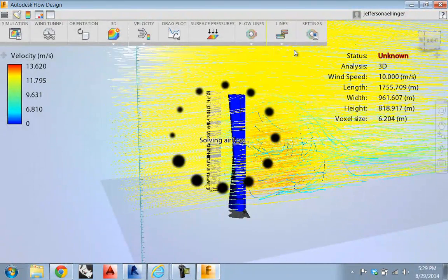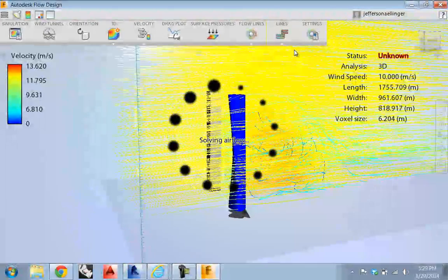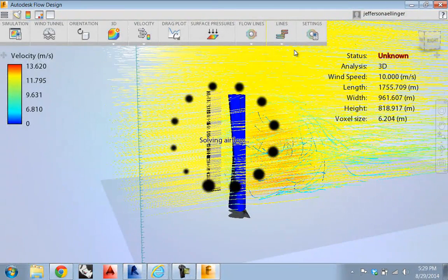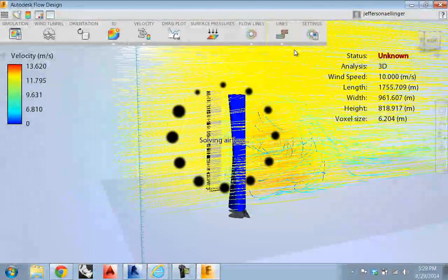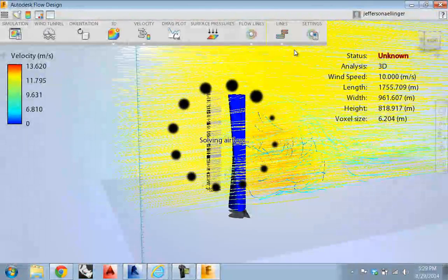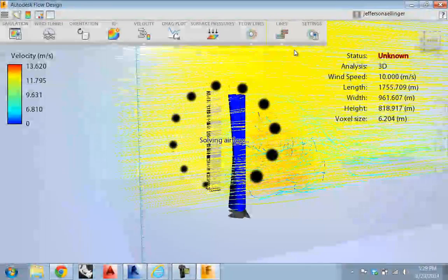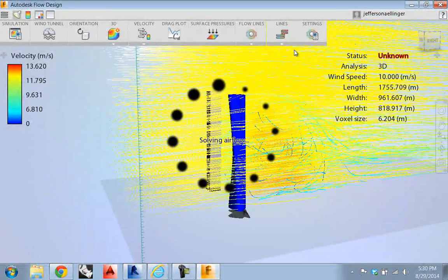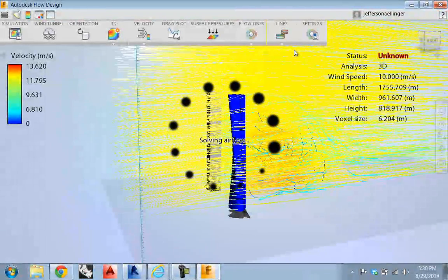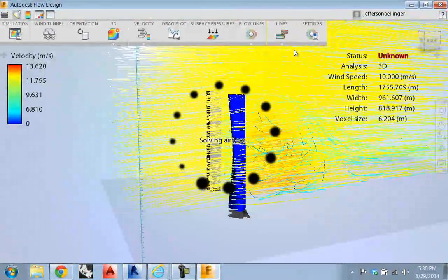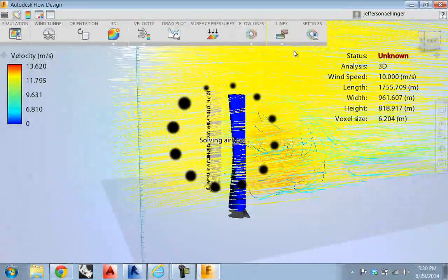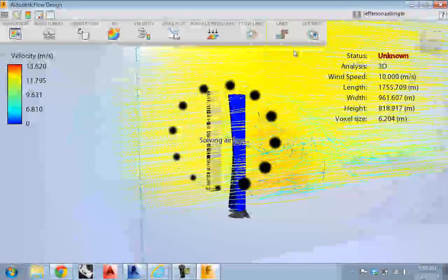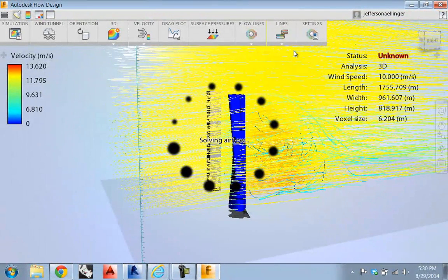When you're starting the question about moving through the room, in order to get accurate results of the airflow in the room, your voxel size really needs to be somewhere around 1/2 inch, so that you're getting a good representation of what the airflow is. I don't know if you can do that on a laptop though. It's pretty high resolution. Even this might crash the machine at this point.